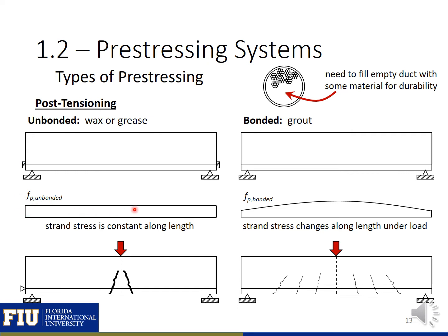So you'll have an average stress along the length caused by loads, and then also you're going to get one or two larger cracks. So when you have a crack open up or two cracks open up, these cracks will grow, and you won't have distributed cracks along the length of the structure.